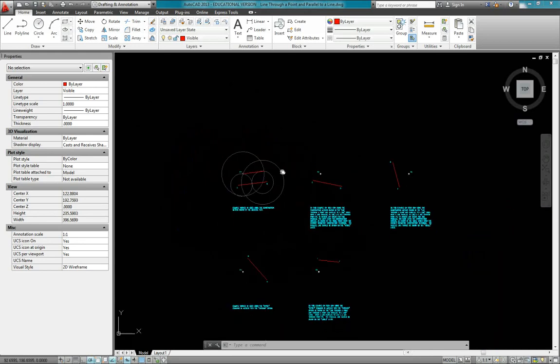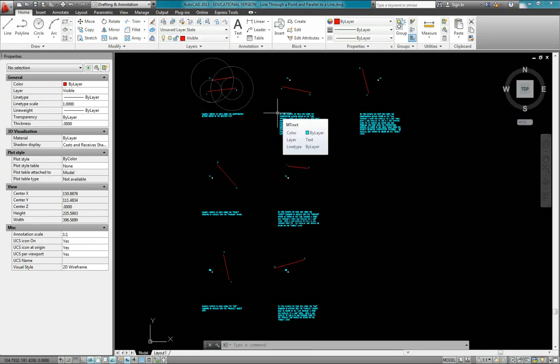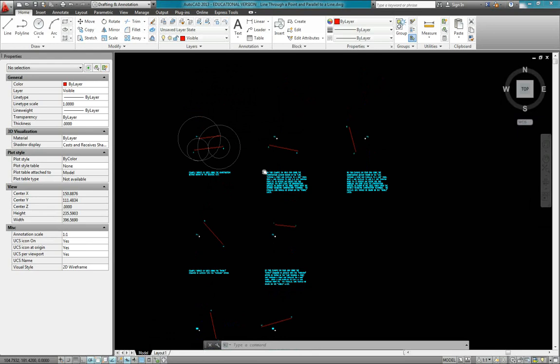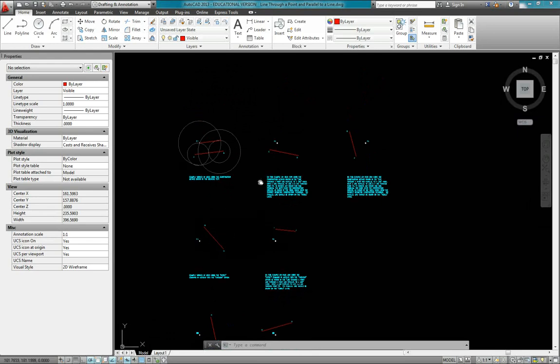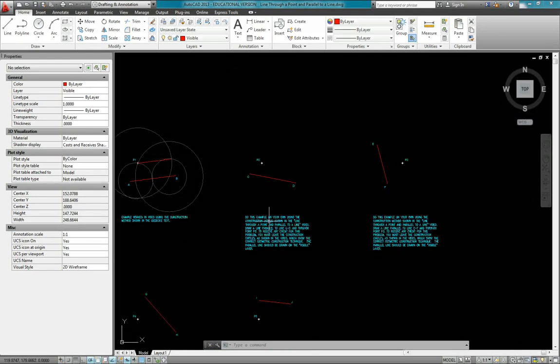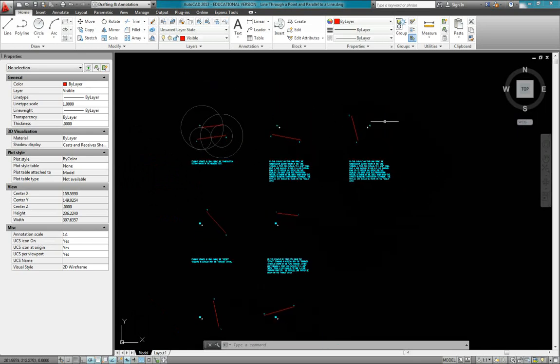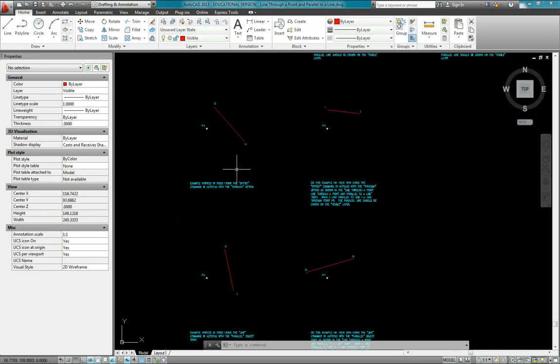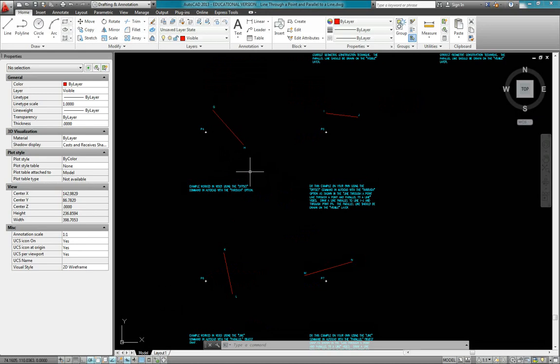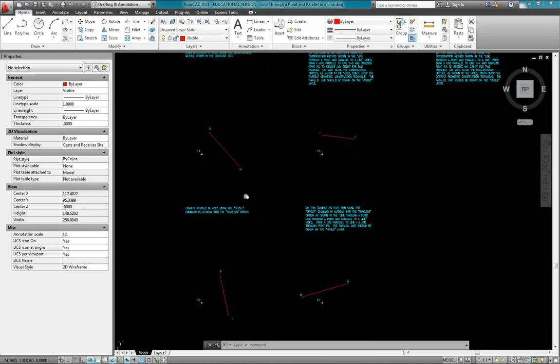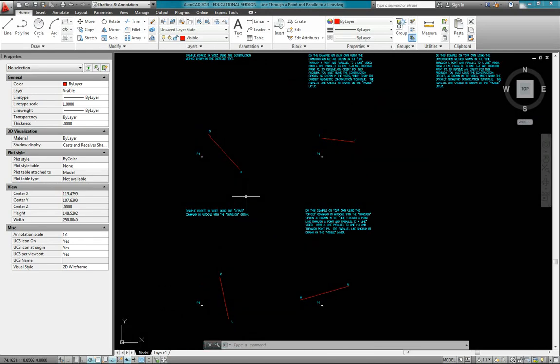Okay, so AutoCAD has some tools that will greatly increase your efficiency. Oh, by the way, I said it right here in the directions, but make sure you leave all these construction circles in your work for these two examples that you'll be doing on your own. All right. So the next way to do this is to use the offset command with the through option.